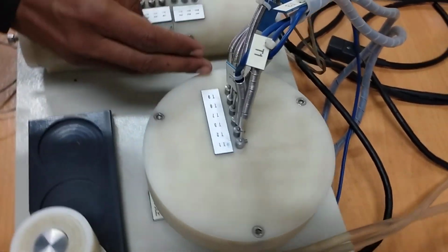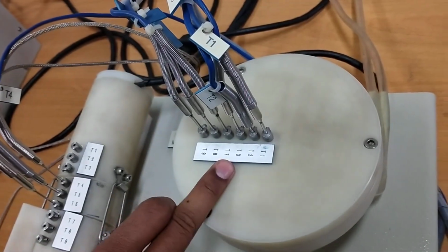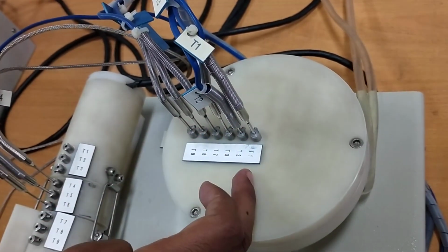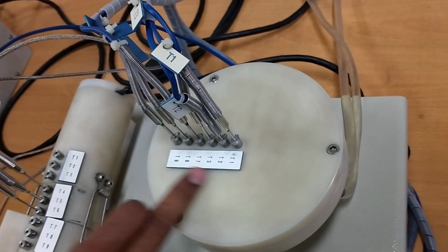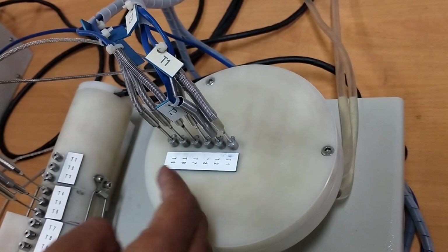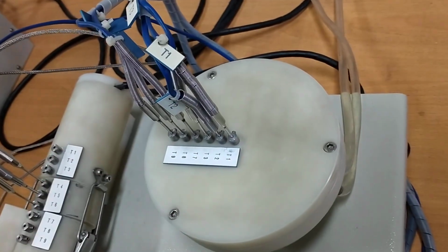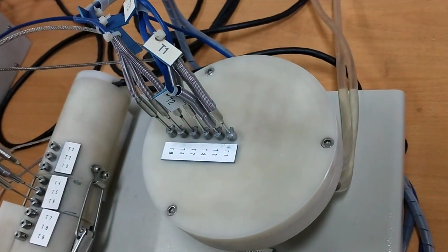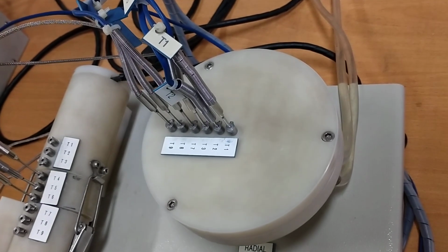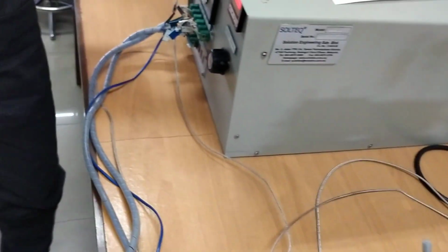From T1 to T9, as you go from the center of this cylindrical plate to the outer periphery, you observe decreasing temperature, and on the outside the water absorbs the heat. We have to find the thermal conductivity of this material using Fourier's law of heat conduction. From the theory, you see Fourier's law of heat conduction for the experiment.